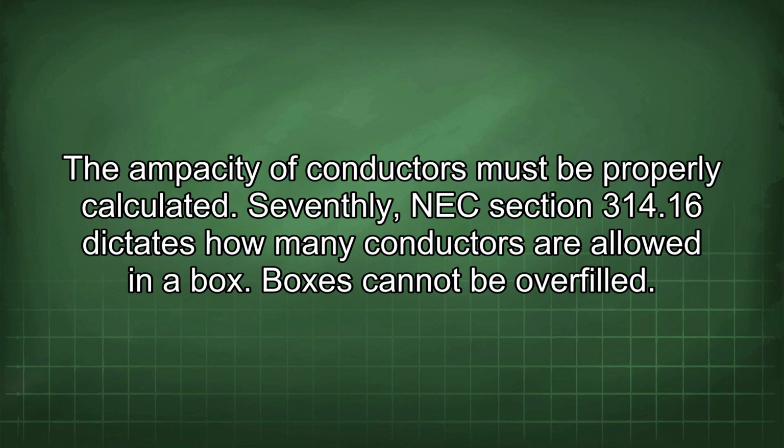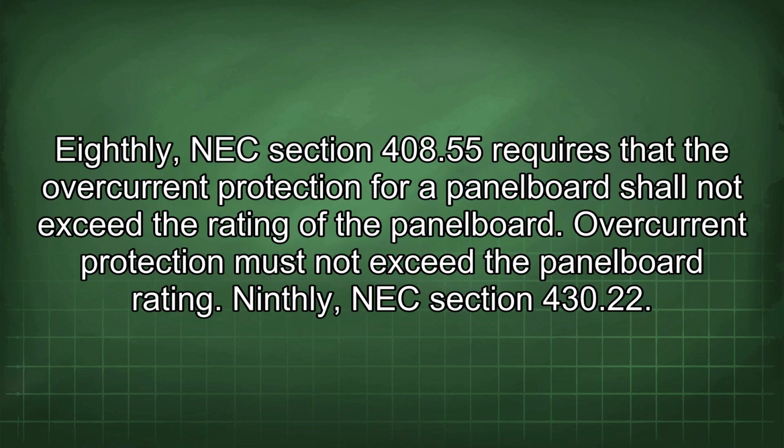Seventhly, NEC Section 314.16 dictates how many conductors are allowed in a box. Boxes cannot be overfilled. Eighthly, NEC Section 408.55 requires that the overcurrent protection for a panelboard shall not exceed the rating of the panelboard. Overcurrent protection must not exceed the panelboard rating.